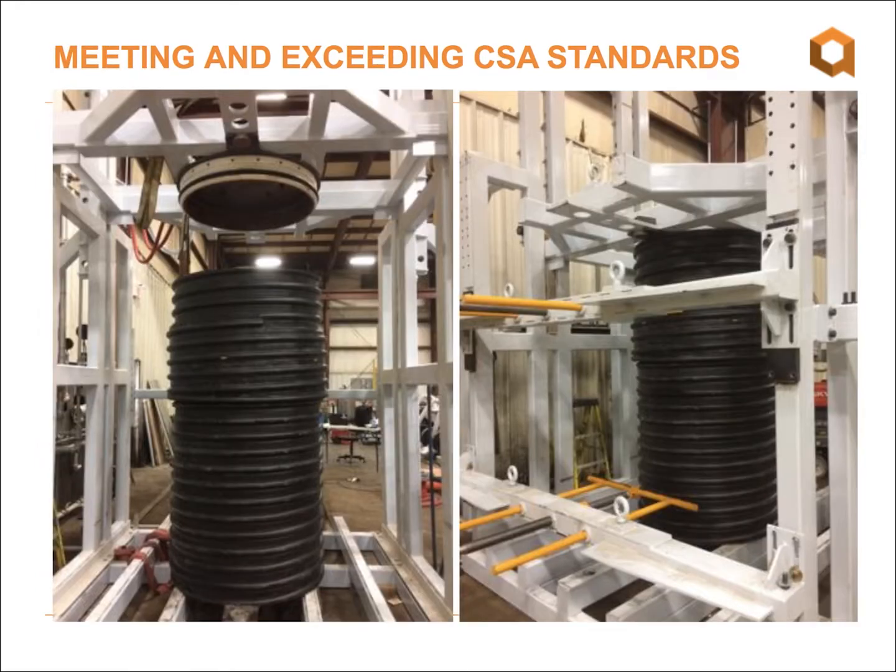Then you want to be sure that your joint meets the requirements of the standard. So this is a joint integrity tester that we had to build at our facility. I know it's a little bit difficult to see because it is black pipe on black pipe, but this is the bell right here, and the spigot has been inserted. We cap both ends, and then the hydrostatic water pressure is raised to 100 kPa for a duration of 10 minutes. Once that is done, using these metal bars here, we deflect the joint by 5% and also do a hydrostatic test at 100 kPa. And once the pipe is emptied of the water in it, a vacuum test is also conducted.